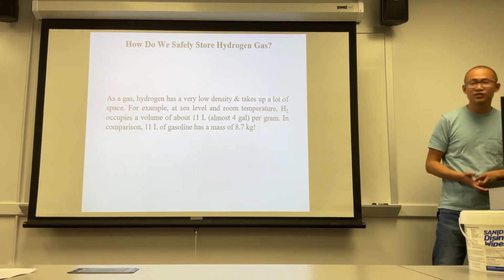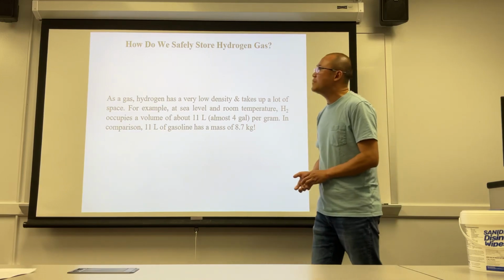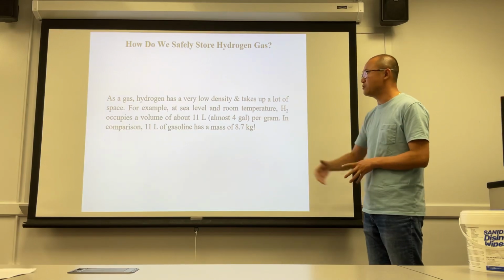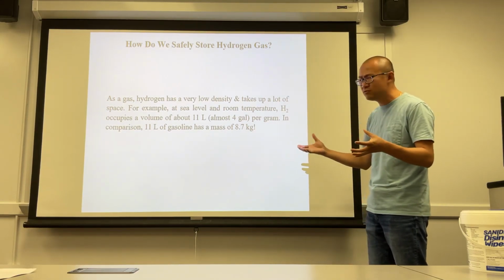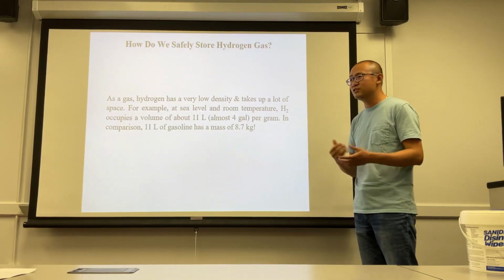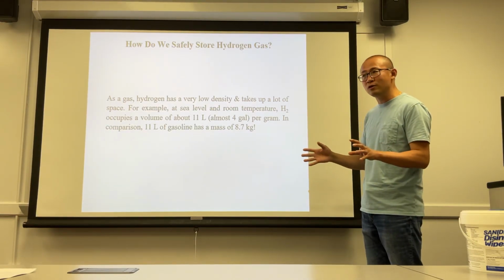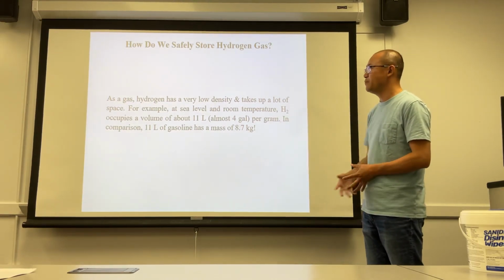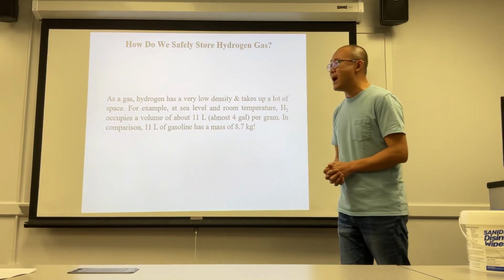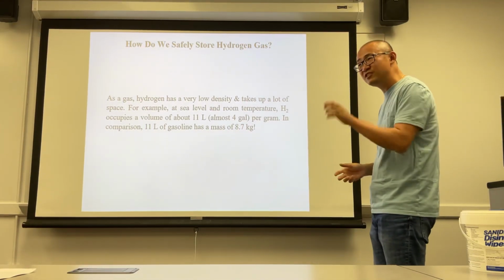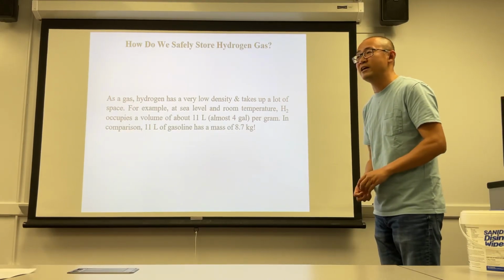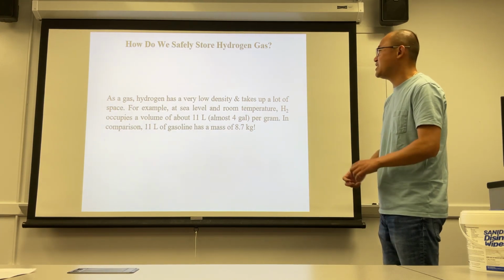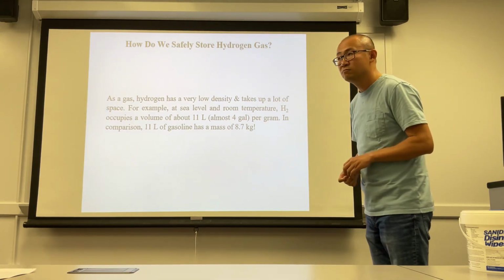The next challenge is how to safely store hydrogen, especially in a tank in a car. Here is something to think about regarding storage. You may think it's nothing bad to store hydrogen in a car, just use a tank. But it's not that straightforward, as it would be for a propane tank, because as a gas, hydrogen has a very low density, since it is made of two small hydrogen atoms. That means hydrogen gas takes up a huge amount of space.